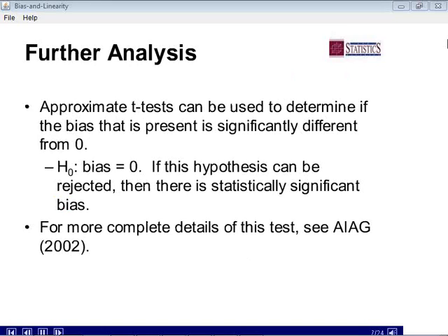Now, from that, you've got two things. You've got bias by definition. Then you've got that percent bias that you can examine to see whether it's too large or too small. And too large or too small is dependent upon what it is for your particular part and your field and your operating range, how large is large.